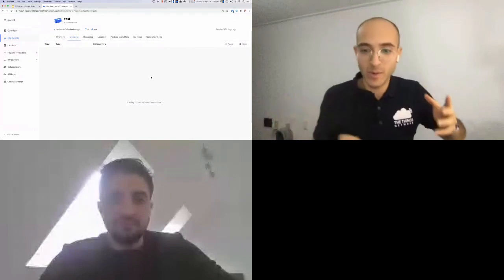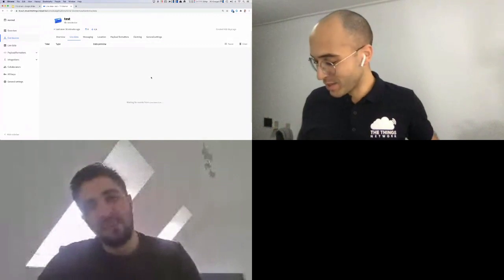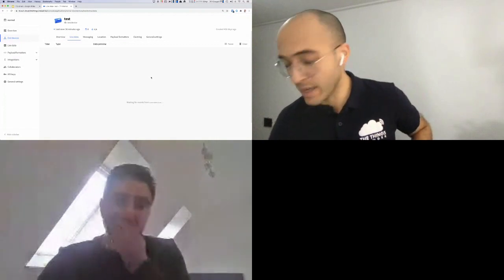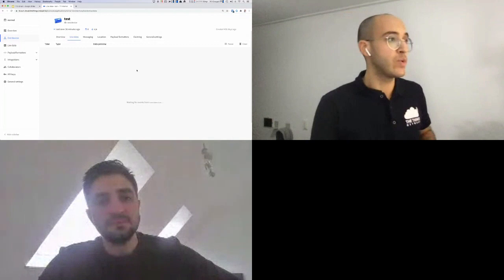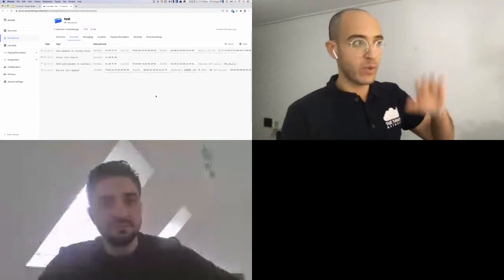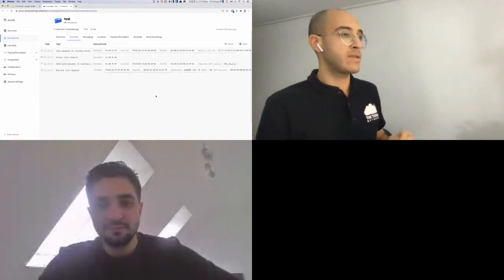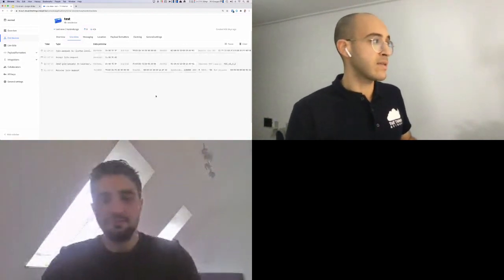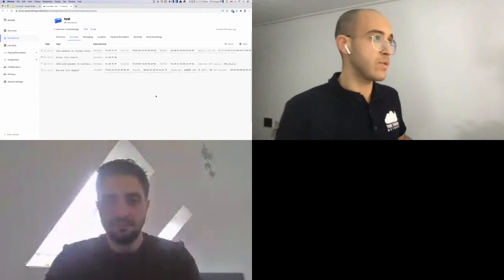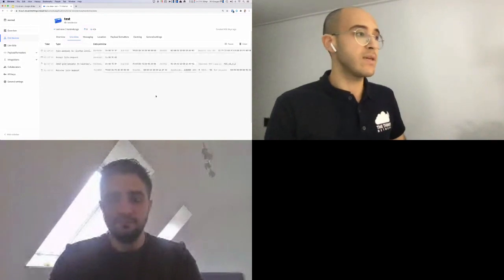This is a live demo, so be nice to me. I hope it works out. I have the sensor edition connected here to the power supply because you can connect it to AA batteries, but I'm going to power it now, and it should try to join. Yeah, it's trying to join. If you are familiar with LoRaWAN, this is just trying to join. We're getting some nice RSSI here, and it's doing over-the-air activation, and it successfully joined. Maybe I can also make my screen a bit bigger in case you guys don't see what's happening.